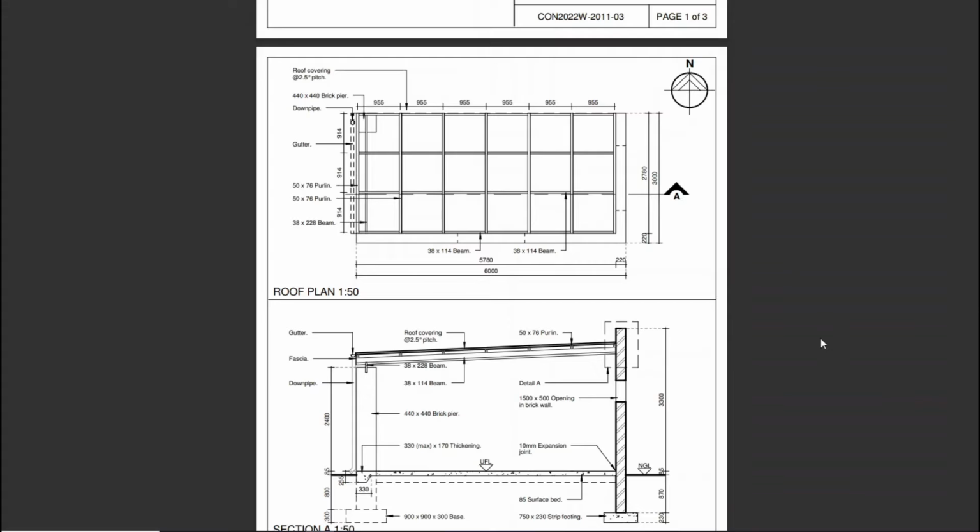So when I looked at this, I was a bit surprised. A couple of rules to take note of. Here is a primary beam. And here's our nice cross-section of a primary beam. One end is actually bearing on the column, so there's no connector for that main beam. And the other end over here is going to be fixed into a wall.